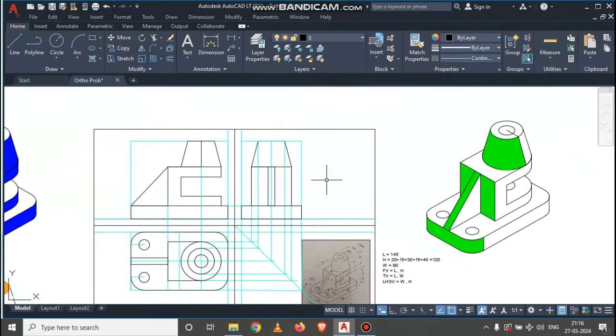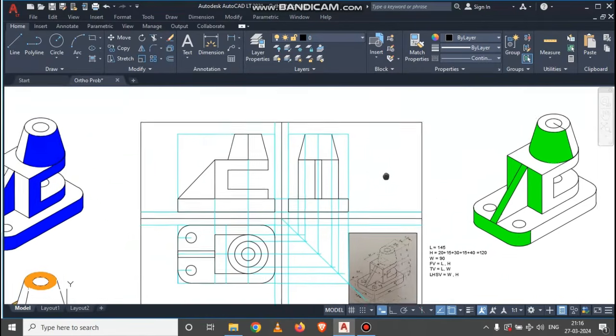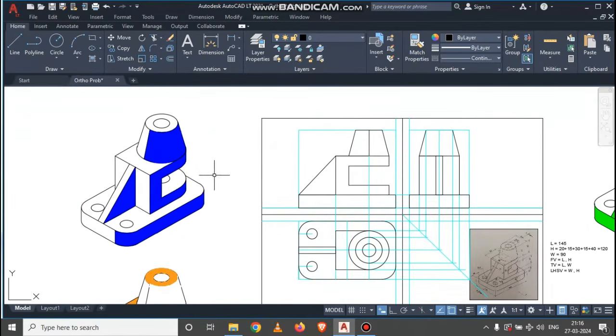Now to represent the hidden surfaces in all the three views, we need to understand one rule. Suppose this will be the direction for the observer for the front view. Okay, so while looking in that direction, the observer is unable to observe these two circles present over this horizontal rectangle. Along with that, he is unable to observe this inner circle present inside this conical surface. Again this circle as well, that is present over this horizontal surface.